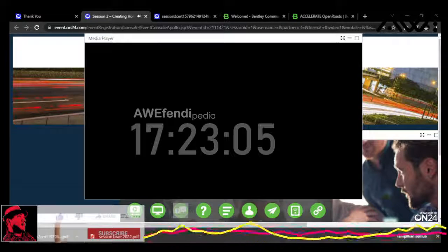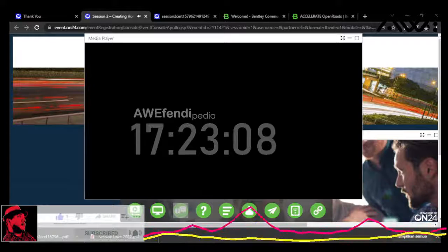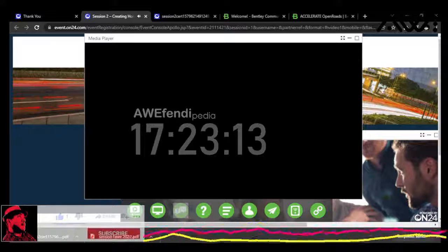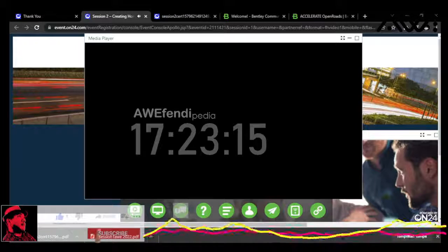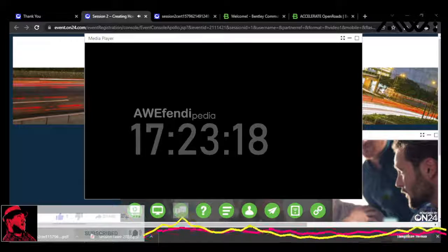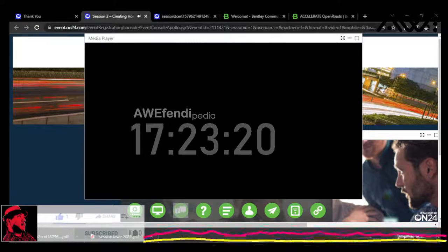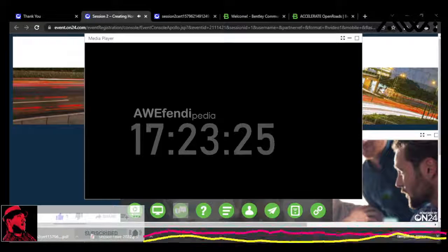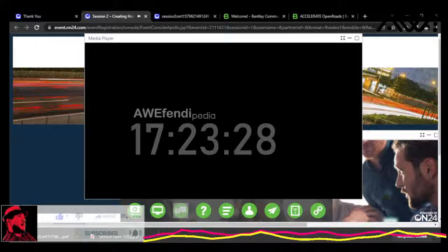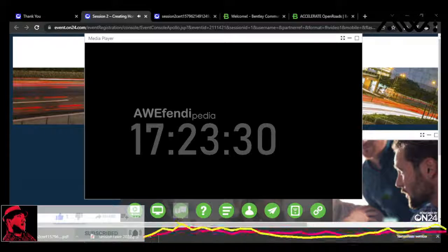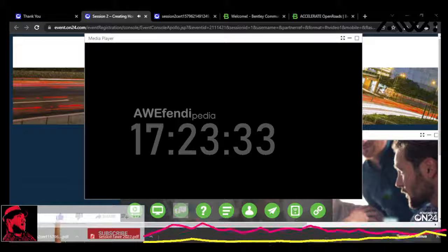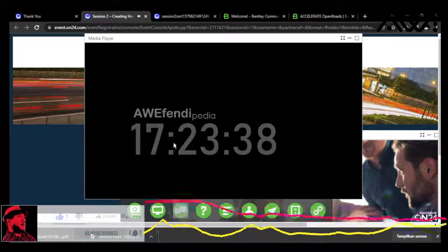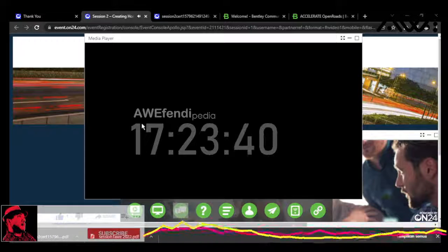I'll select the element, and then I'll select the start point, meaning the PC of this particular curve. I want that to start where my tangent ended, so I'm going to snap there, left click, and I'm going to begin laying out this curve. Much like with the tangent, I have a heads-up prompt with a field where I can input data. So for the radius, if we refer back to our existing information, we'll see the radius is 2002. So I can, again, key that in, click the tab key to lock it, and now I have that radius placed, and I can data point.